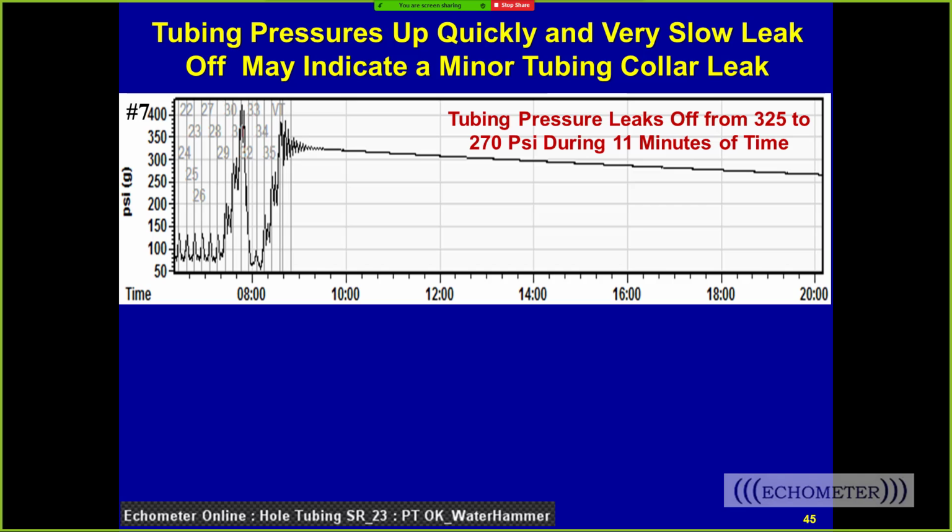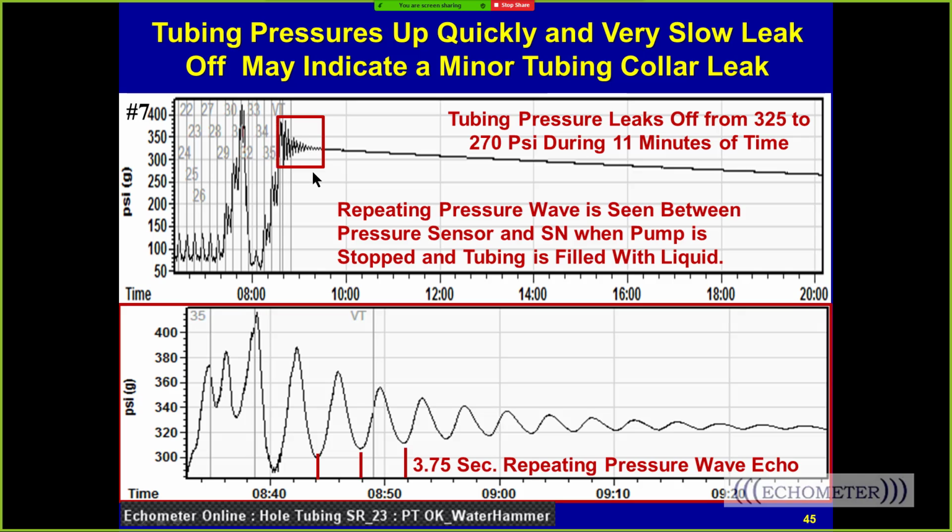Now, one of the things that we noticed when we do these pressure tests was, what's that? What's that noisy thing right there on the acoustic trace when we first shut the well? Is that a leak? What is that? Well, if I take this right here and expand this to the full scale, this time from about 9 seconds to 9.5 seconds, I see that this is a wave.